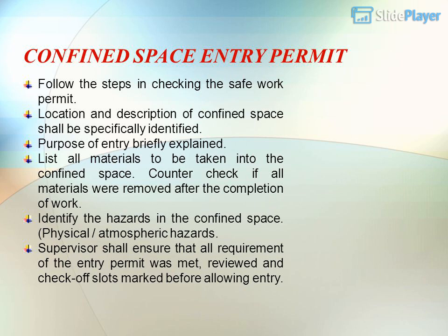Follow the steps in checking the safe work permit. Location and description of confined space shall be specifically identified. Purpose of entry briefly explained. List all materials to be taken into the confined space. Counter-check if all materials were removed after the completion of work.